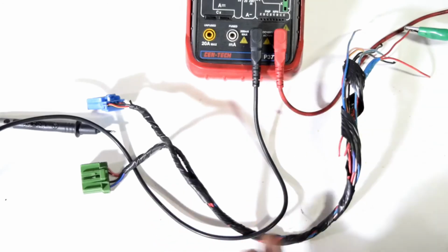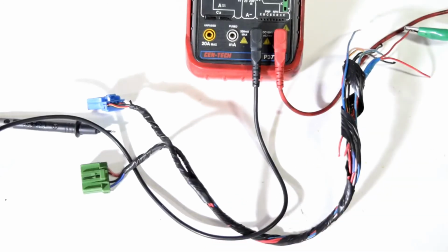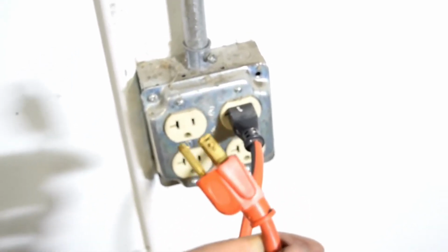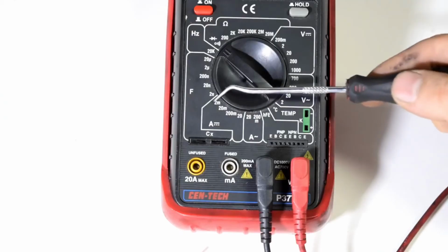Now I did this test on a rather small scale, but this can be done on a much larger scale, or in other words, larger circuits, or even smaller circuits than this, like a motherboard of your computer. A word of caution though, whenever you test for resistance or continuity, you have to make sure that the device is not powered, so either unplug it or remove the batteries. Next up, how to measure amps.